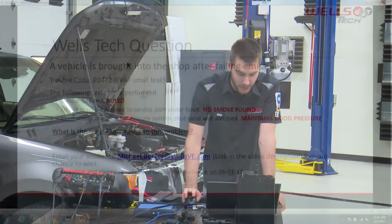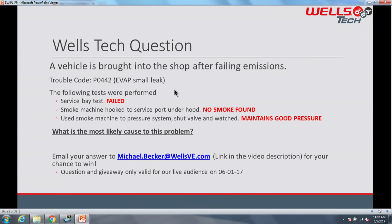So a vehicle is brought into the shop after failing emissions. Check engine light is on with a code P0442 EVAP small leak. These following tests were performed. There's a service-based scan tool test done. That test failed. It has a leak. A smoke machine was hooked up to the service port under the hood. No smoke was found. And the smoke machine was also used to pressurize the system and then watch the gauge. The gauge is maintaining pressure, so it is not showing a leak with pressure. What is the most likely cause of this problem?